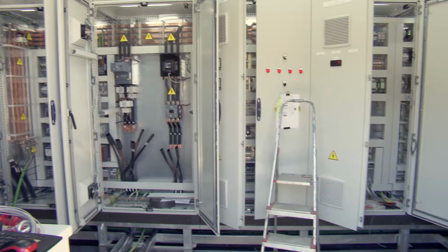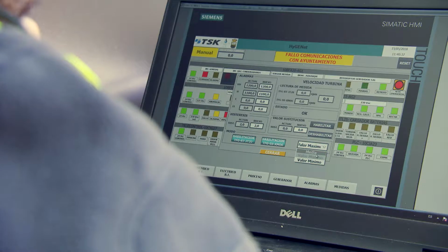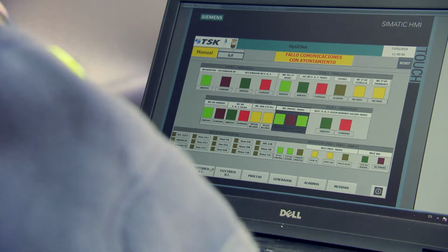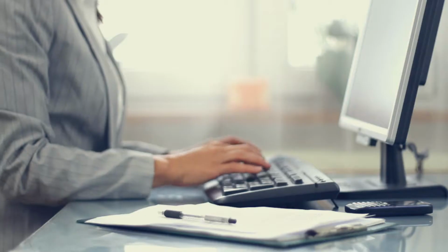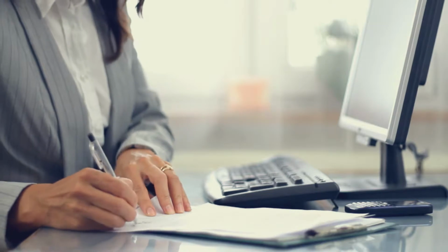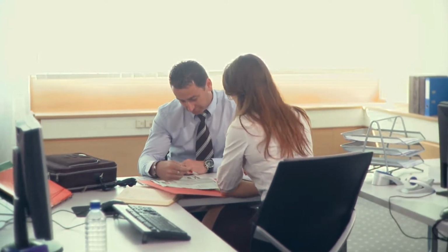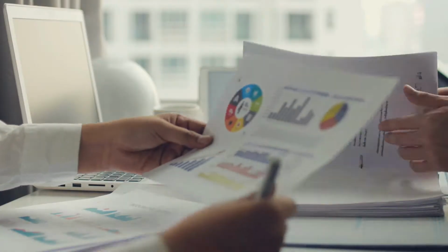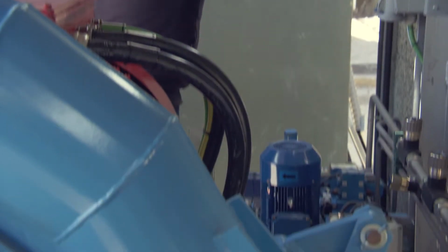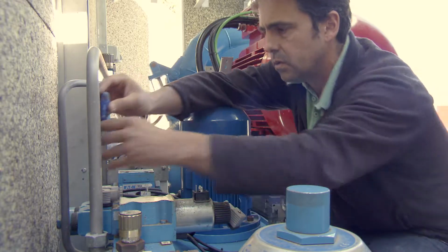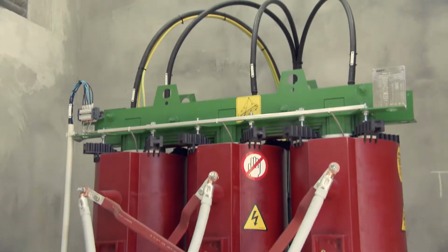With regard to the operational control of the installation, the devices are fully automated, allowing them to be monitored from a control panel to ensure operation under optimal conditions, manage energy flow, and generate actions in response to any anomalies. Apart from operational control, the generating facility also requires dedicated administrative management to monitor funds received from electricity companies for energy sold to the grid, as well as the payment of taxes and fees or the purchase of insurance. Regarding maintenance, a preventative maintenance program as well as a protocol for corrective maintenance actions in the event of failures or breakdowns must be drawn up in accordance with the maintenance plan of the installation.